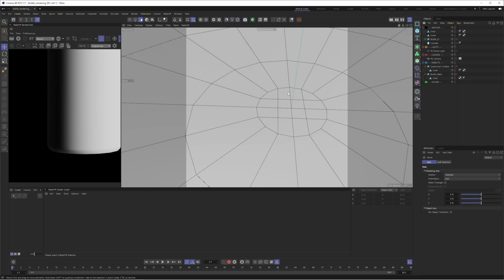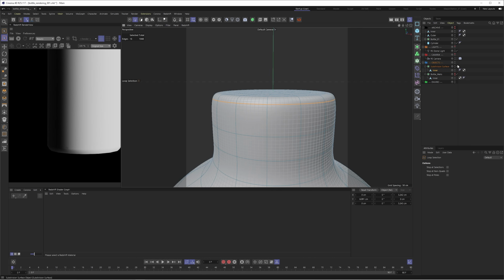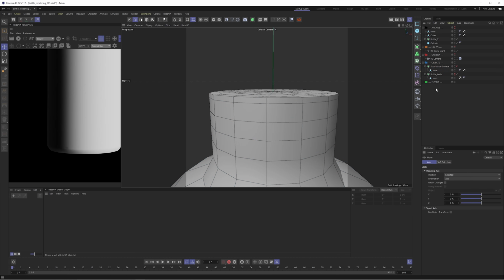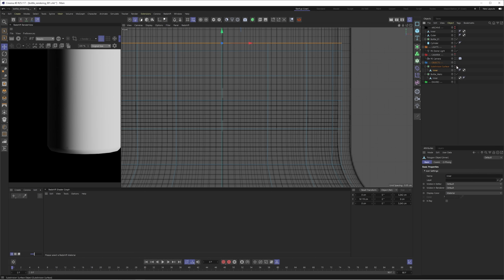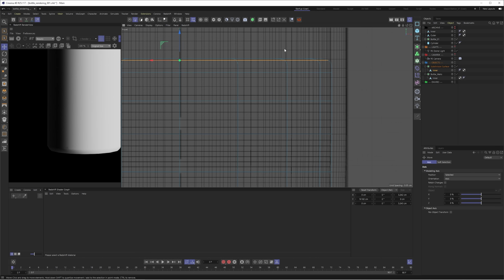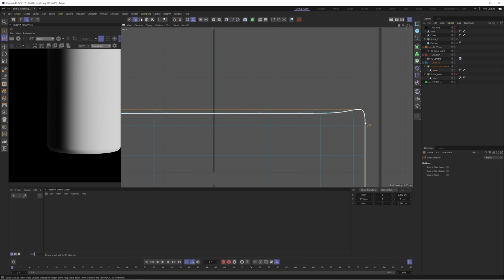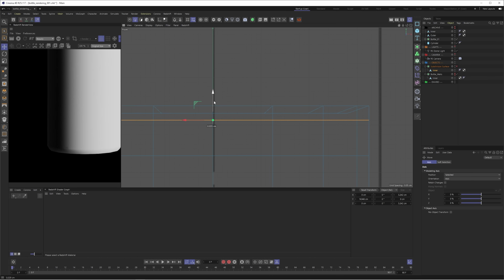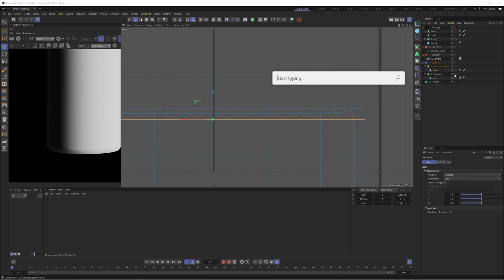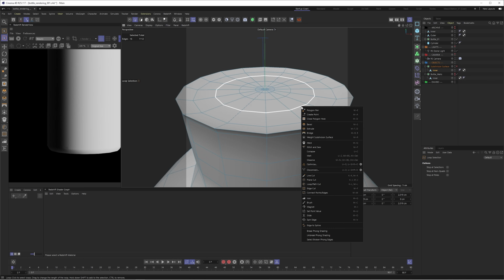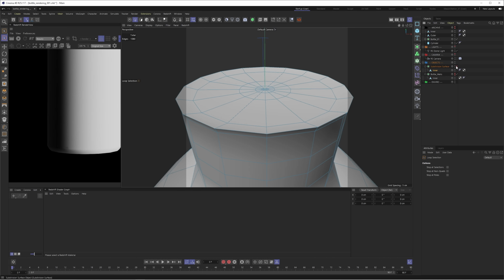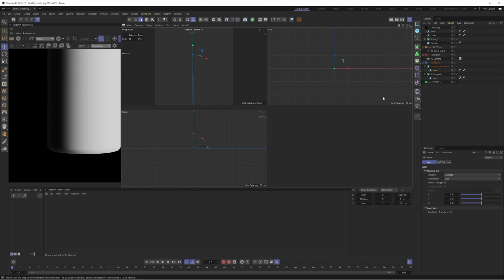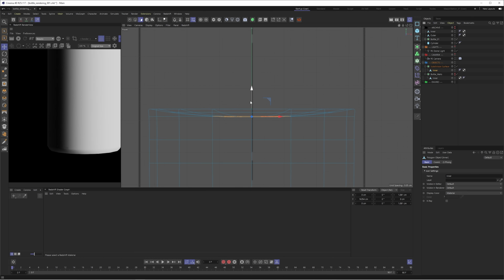grid shape. This is looking much better, but our liquid is too rounded on the edge, so let's add some additional loop cuts. Finally, to simulate surface tension, we need to edit our liquid so it curves towards the edge of the bottle. To do this, let's move the outermost edge upwards, and we may also have to rejig some of the other edge cuts to sharpen this edge even more. I decided to dissolve some of the edges to make the curve smoother and then go into polygon mode and select the innermost polygons and move them down slightly to make the curve more prominent.